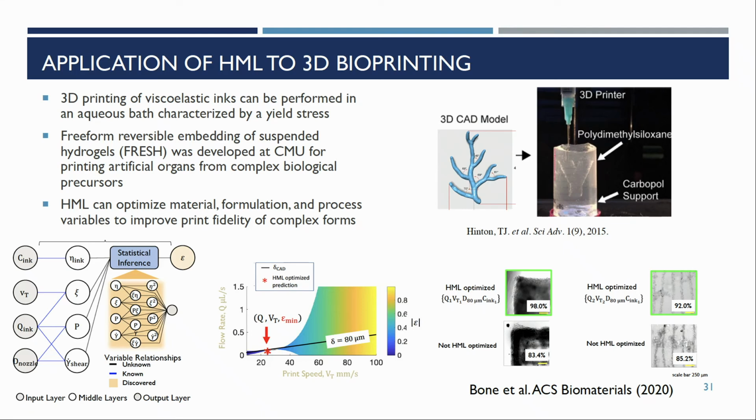These are all different flavors of variables, but the algorithm is still able to manage these, and we can do some optimization shown here and identify conditions where, for example, we can optimize the printing of corners versus lines. All this is guided by an underlying knowledge of the dependence of the viscosity on the shear rate and the concentration, for example.